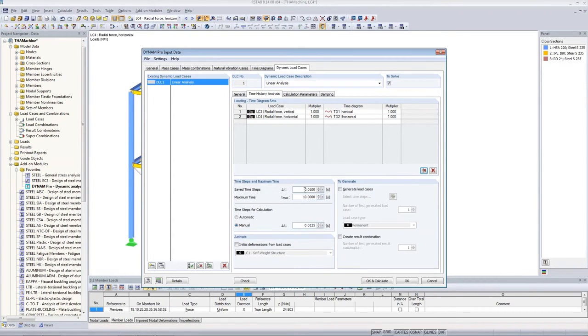It's even smaller because I have defined my save time step this way. The save time step is just for a smooth curve later on. So if you want to have a smooth graph, a time course graph, then you have to reduce the time steps here. If you do not need this, then you can increase the time steps because this saves, of course, memory and calculation time because also the saving takes some time.